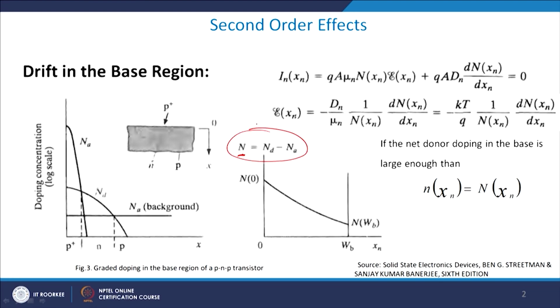So you had, let us suppose, Nd as 10 to the power 19 and Na as 10 to the power 15 or 16, then you subtract both of them and that is the effective number of dopant species. If we have 100% ionization, I would expect to see that many free charge carriers. If Nd is greater than Na, the free charge carriers are electrons; if Na is greater than Nd, the free charge carriers as holes will of course be available to you.